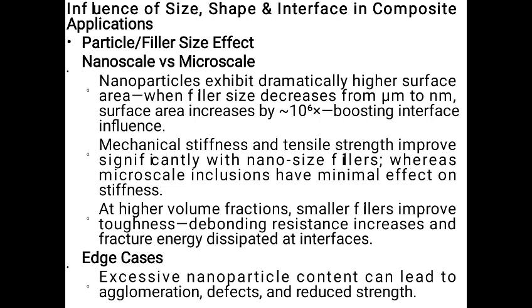Influence of size, shape and interface in composite applications. Particle or filler size effect. So here we shall compare both nanoscale versus microscale particles. Nanoparticles exhibit dramatically higher surface area where the filler size is decreasing from a micrometer range to nanometer range and the surface area increases in the range of 10 to the power 6, thereby boosting the interface influence.